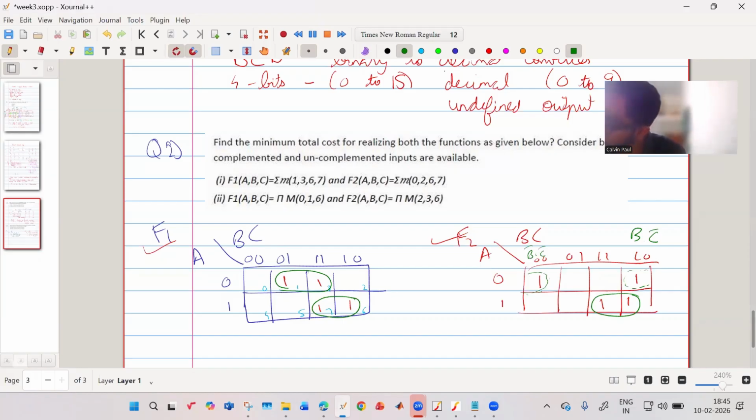So that is the reason why we construct the Karnaugh map in this way: you have 0 0, then you have 0 1. It is changing one bit at a time. So you must always remember your Karnaugh map should be constructed in a way that it changes one bit at a time. But we cannot do this for the rightmost and leftmost. We have to understand that there also it is changing one bit at a time.